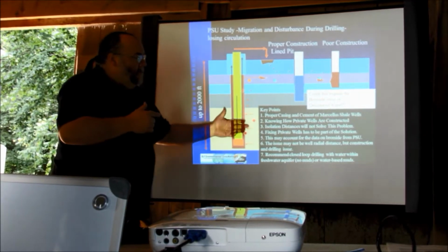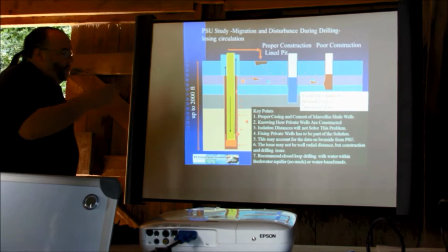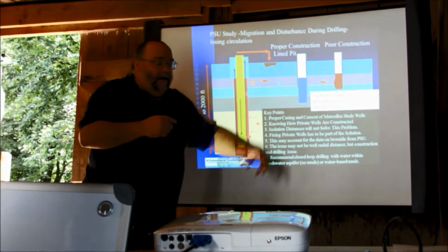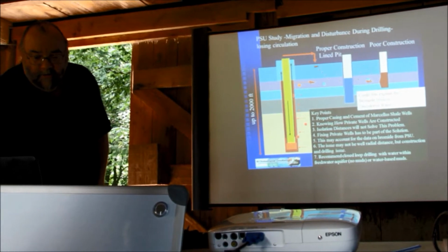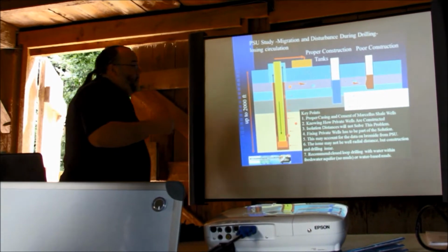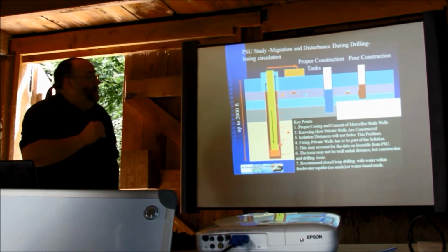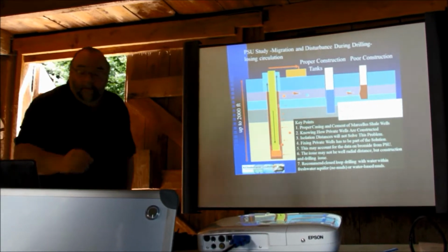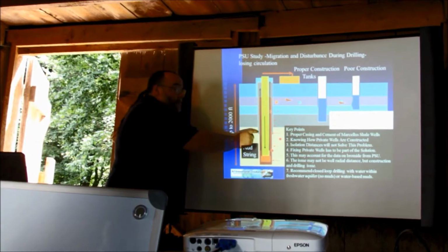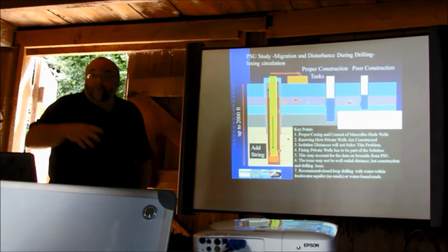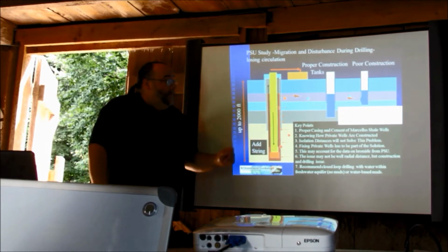So this was suggested. Penn State did a study where they were trying to suggest that some bromide spikes they saw in shallow wells might be associated with this. Some of the changes companies were making is going to closed loop drilling, putting all that back in tanks. Still not a regulatory requirement. One of the things companies have been doing is adding more strings. So instead of just one freshwater string, multiple strings to seal off and prevent that migration.